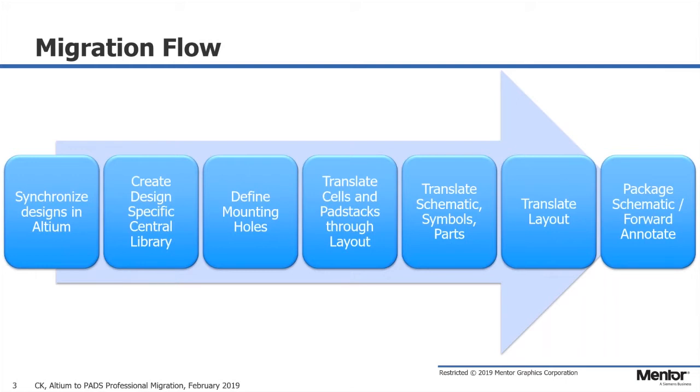And then the last and probably the most important step is we're going to want to make sure that we package our schematic and forward annotate our design. So this is going to make sure that our schematic in Pads Designer, as well as our layout in Pads Professional Layout, will be in sync so that any changes made will be synchronized between the schematic and layout, and that we can move forward with any edits in our design and make sure that the integrity is in check.